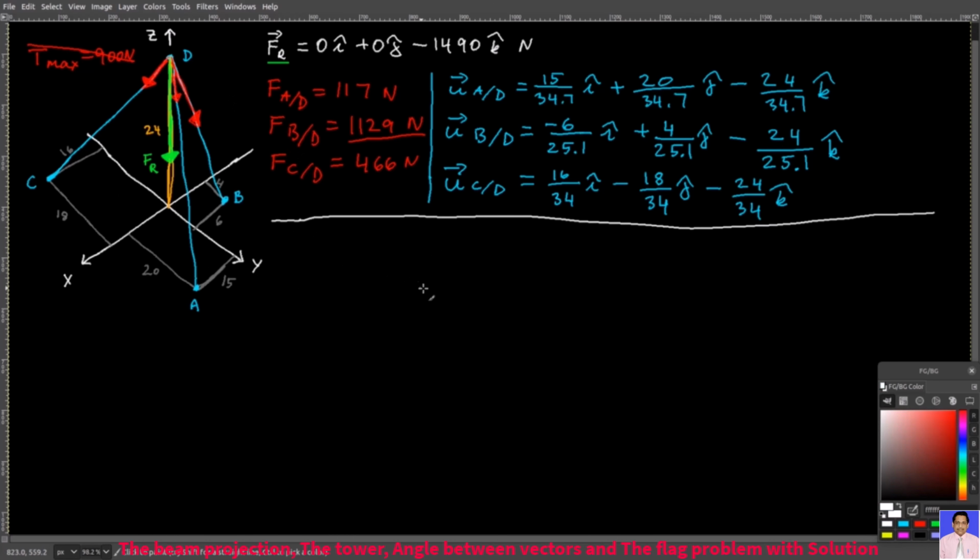And now, I would like you to perform a reverse operation, but using the dot product. I would like you to take these three forces, and use the dot product in order to obtain this resultant force again.